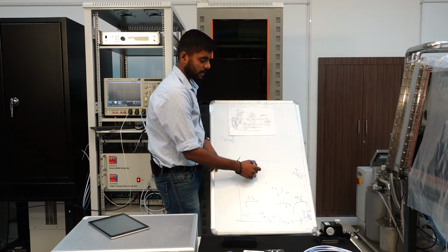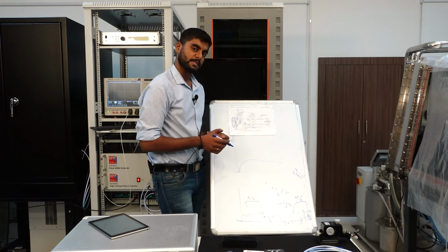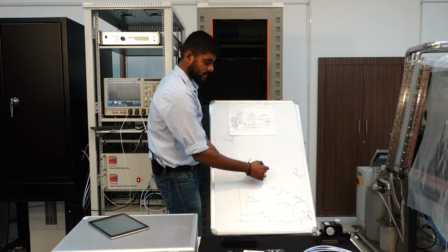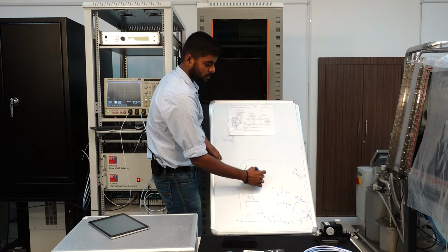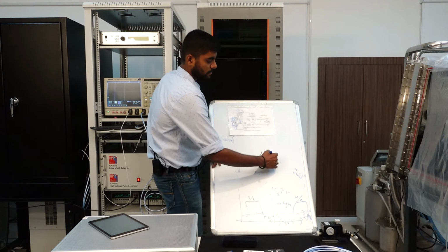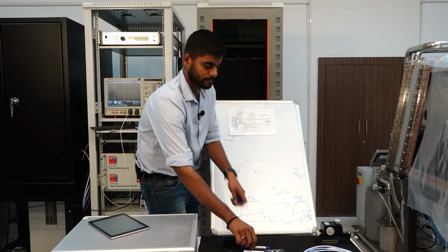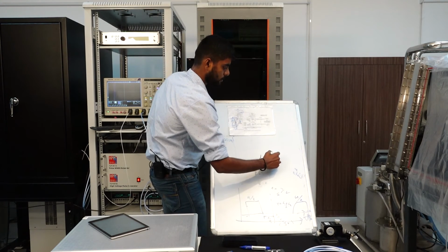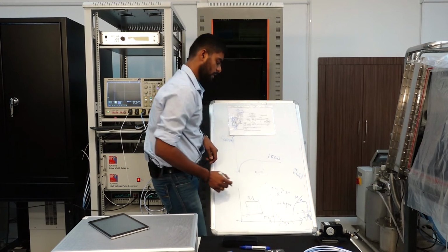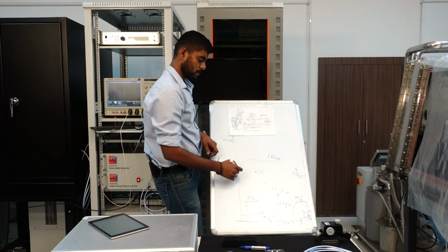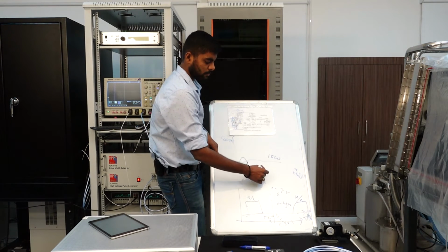Your machine model has a very impulse-like waveform here, something like this, which does not have a time period of more than a few nanoseconds. HBM has a time period of 150 nanoseconds. Sorry about that, 150 nanoseconds. And then you also have a CDM pulse, which is oscillatory in nature but decaying as well.